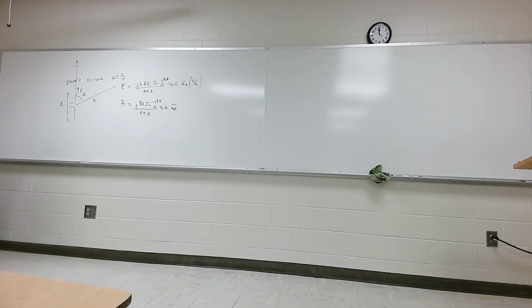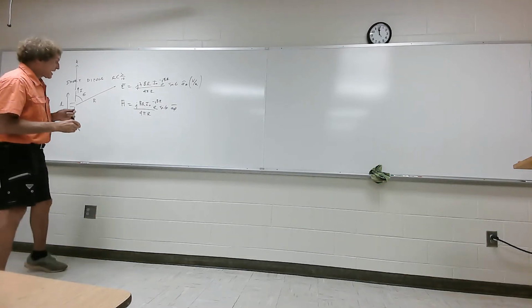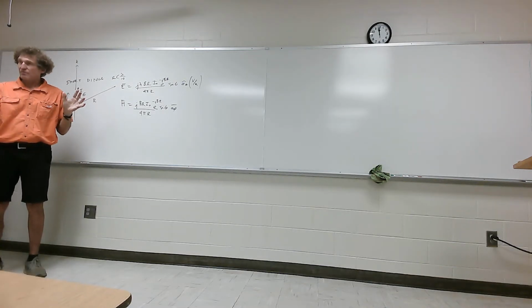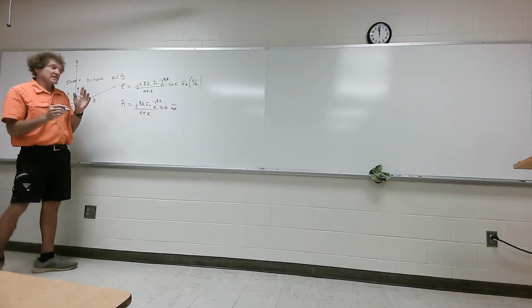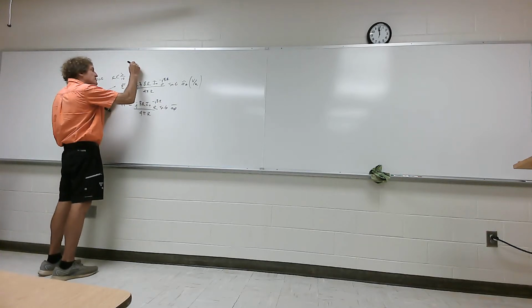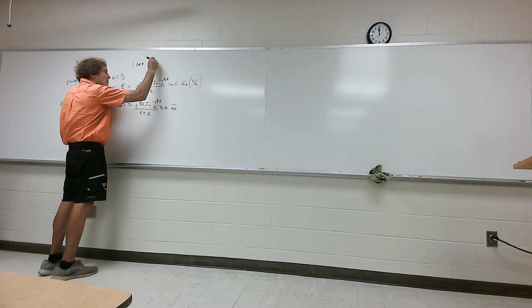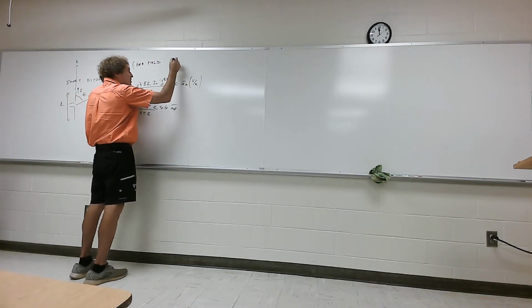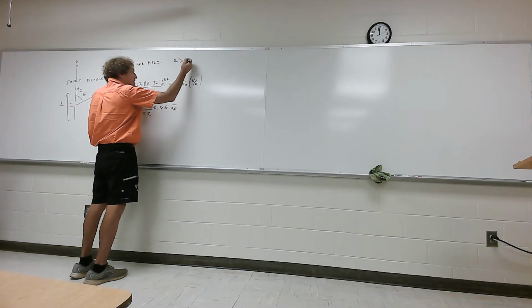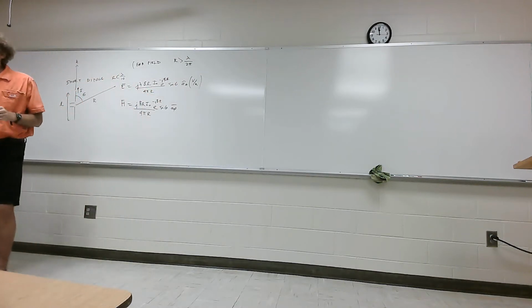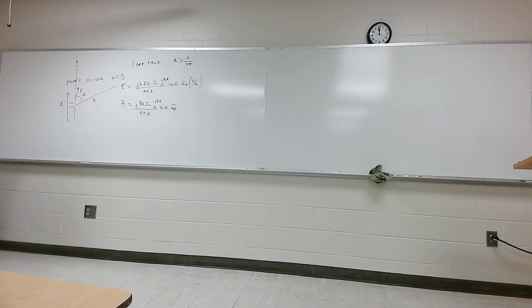All right? After that, I have to make one statement too. We talked about the far field condition. Do y'all remember that? So this is for the far field. And when you're in the far field, you're at a distance R that's greater than lambda over 2 pi. That's the assumption, that we're at least that far away. And you can see as the wavelength gets longer and longer, you have to get further and further away.